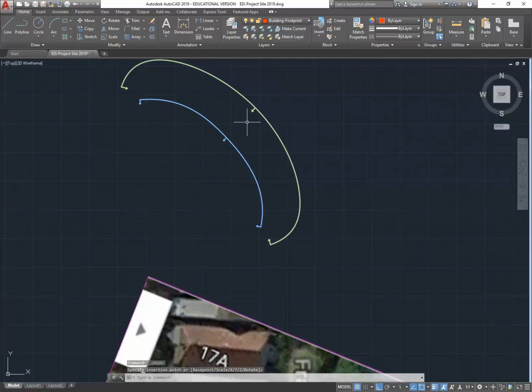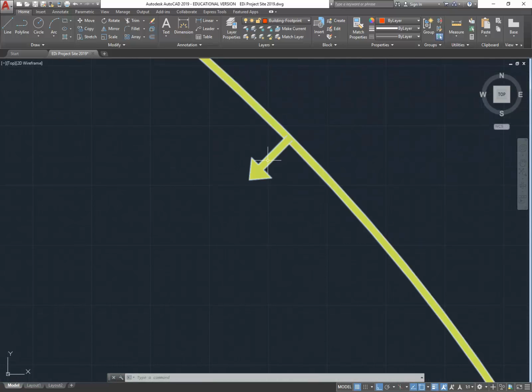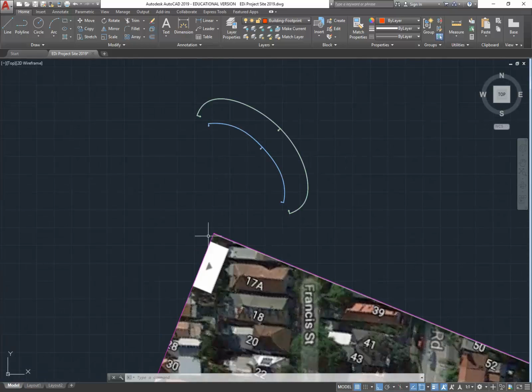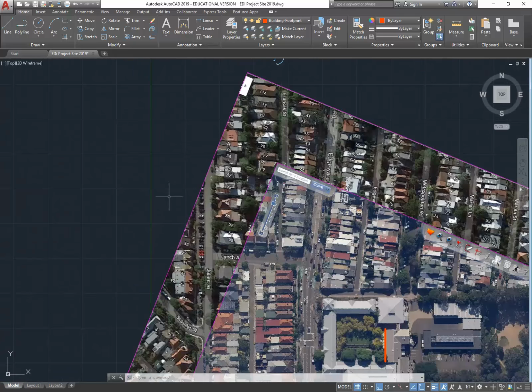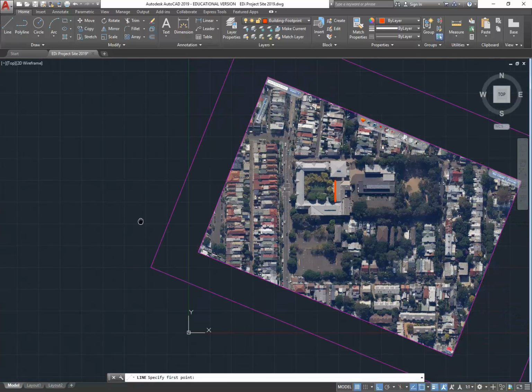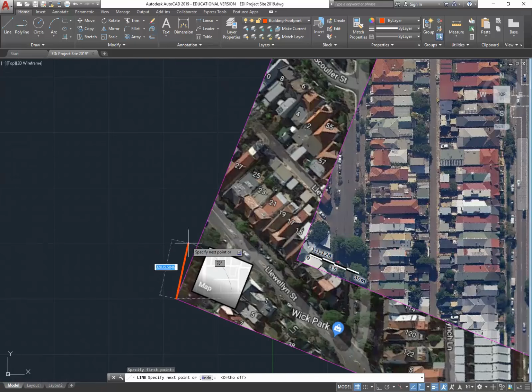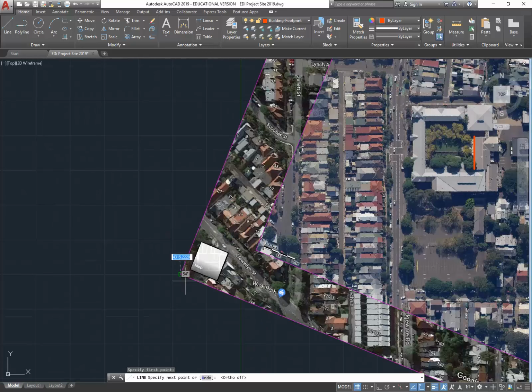So it's set up for the north that I had for the project where I created it. But we of course need to rotate it to use our north. So to help with that, I'll just draw, like a lot of times you do in AutoCAD, an extra construction line and trace the side of the image, just by eye.